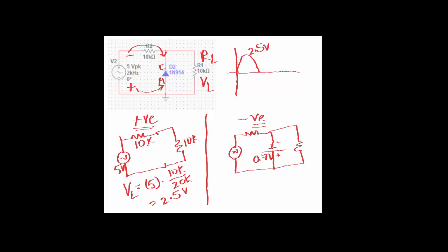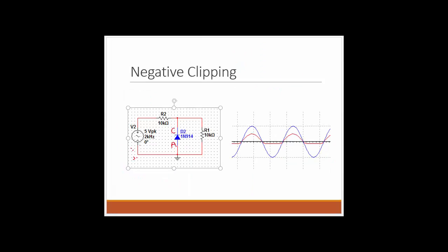So that means when the diode is forward biased, it acts as a 0.7 volt source. Both resistors are 10 kilo ohms. The load is parallel to that 0.7 volt source. So the voltage across the load, if you observe, that's the negative and the positive. So I'm going to collect a negative 0.7 volts. Look at the orientation of the diode. So the output voltage during the negative half cycle is going to be negative 0.7 volts. So that is what's going to happen.